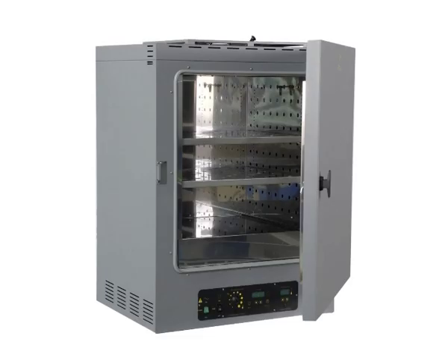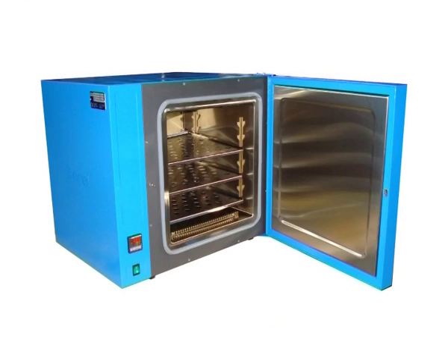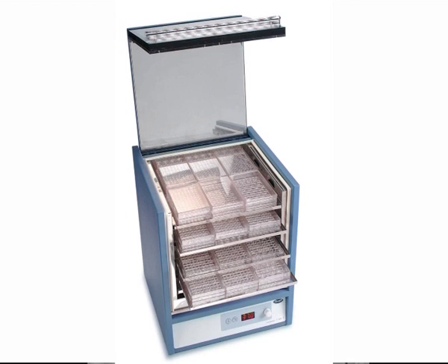Depending on whether the flow of the fluid is artificially induced or natural, there are two types of convective heat transfer, that is forced convection and free convection. The free convection is also called natural convection. Forced convection involves the use of some mechanical means such as a pump or a fan to induce movement of the fluid. In contrast, free convection occurs due to density differences caused by temperature gradients within the system.